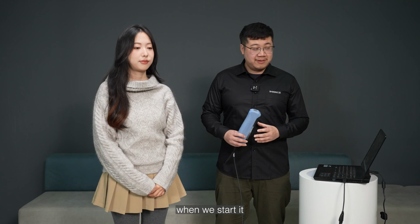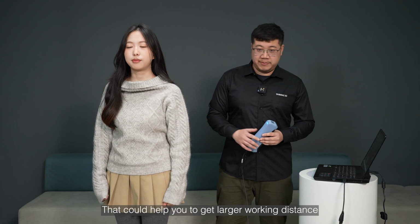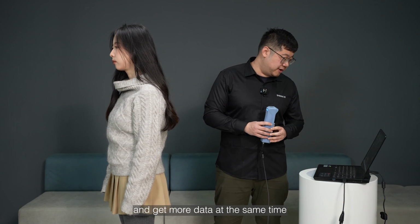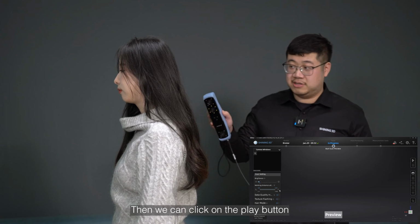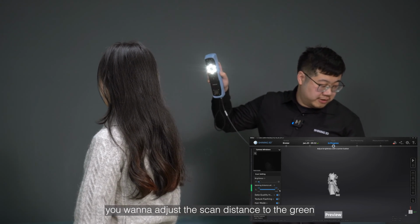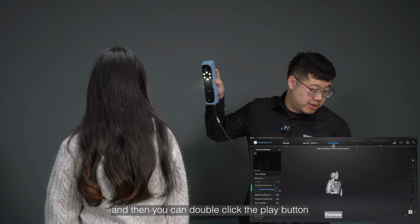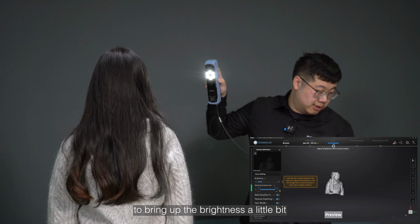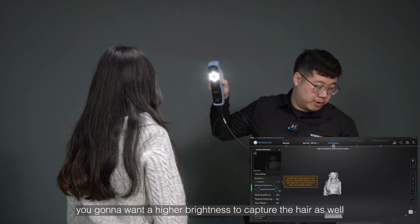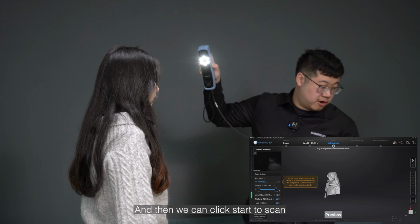Okay, when we start, the first thing you want to do is try to bring up the working distance to 1400. That could help you to get a larger working distance and get more data at the same time. Then we can click on the play button to get into the preview. In this step, you want to adjust the scan distance to the green, and then you can double click the play button to bring up the brightness a little bit, because if the hair is dark, you're going to want a higher brightness to capture the hair as well. And then we can click start to scan.